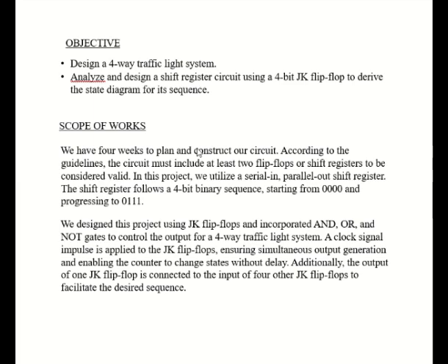For scope of works, we have 4 weeks to plan and construct our circuit. According to the guideline, the circuit must include at least 2 flip-flops or shift register to be considered valid. In this project, we utilize a serial in parallel out shift register. The shift register follows a 4-bit binary sequence starting from 0000 and progressing to 0111.